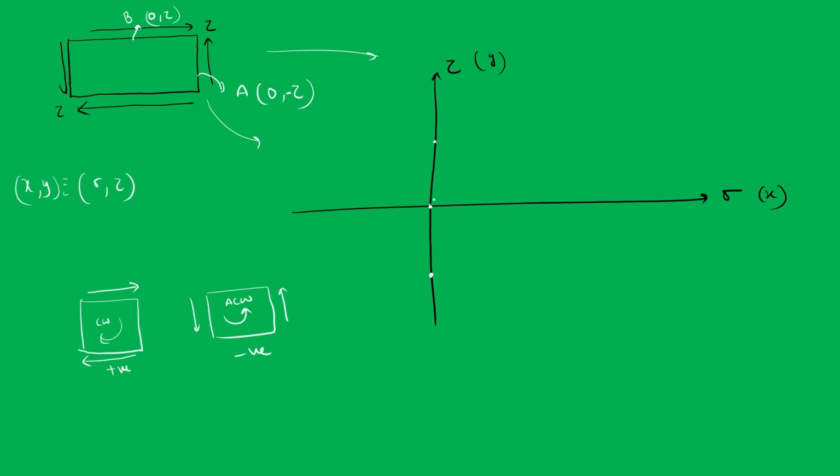So this will be point B, this will be point A, and this entire length we will bisect. It will come here and we will draw a circle. So this will be our circle, and this is 0 comma 0, which is also our center. The center is represented by sigma x plus sigma y by 2 comma 0.